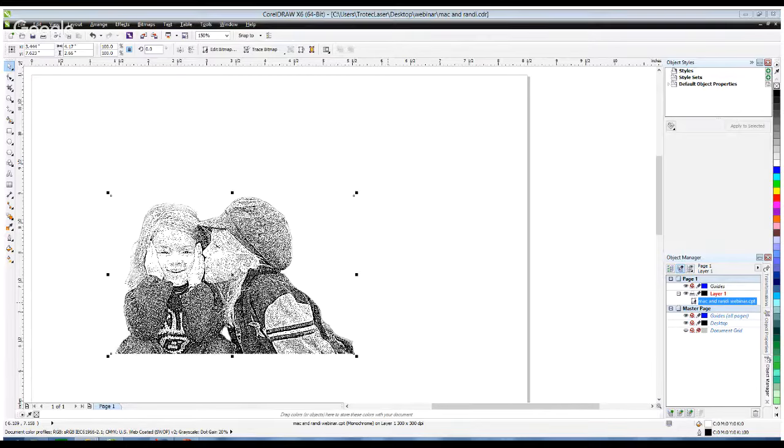A lot of people will transpose that into color or into quality, but when we're doing photographs, we actually don't see that lower quality. So now what ends up happening is I'm actually going to engrave this job twice as fast because I've got half as many lines, and at the end of the day, I'd rather be doing this job twice as fast. So normally I'm running 333 for the actual photograph, and I switch to a black and white mode. You could leave it in order dithering if you want, or you can be in black and white.